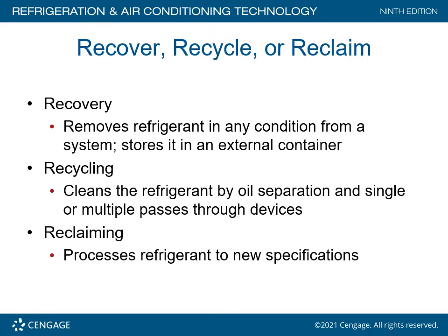I have to remove the R22 that is in the existing old system and store it in a bottle. When the bottle reaches its 80% capacity, I ship that bottle off. In some cases, I get reimbursement for it. In other cases, I basically just get a bottle exchange with an empty one, but this refrigerant goes out and gets reclaimed. Recycling talks about cleaning up the refrigerant by oil separation and single or multiple passes through devices.